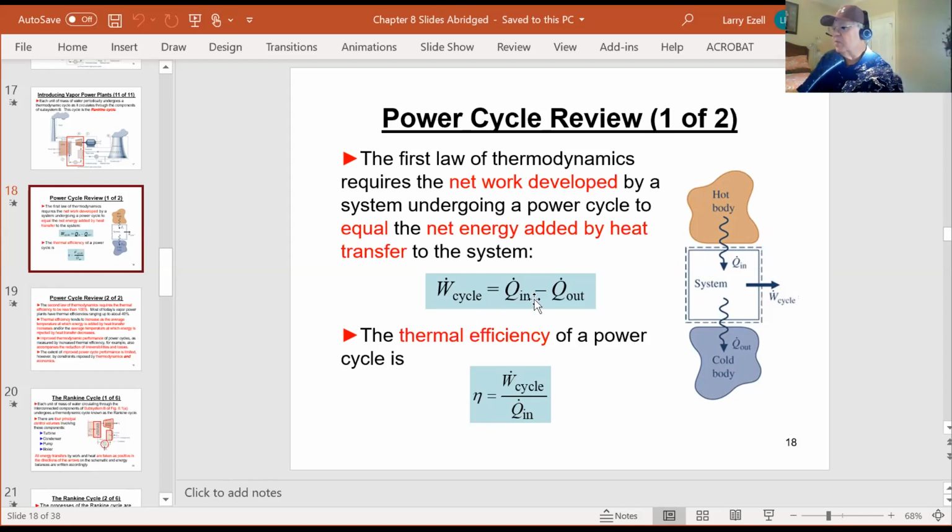And so the work of the cycle, and he uses a negative sign. Q coming in is positive, going out is negative. I would like to put a plus sign here and then let the direction of the heat transfer take care of whether it's plus or minus, but they use the minus, so just be sure that you take the difference between these two if you get confused.